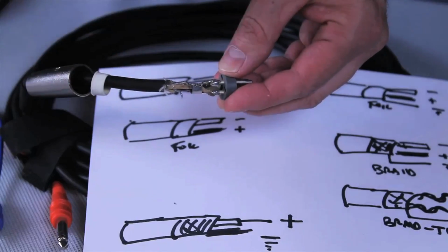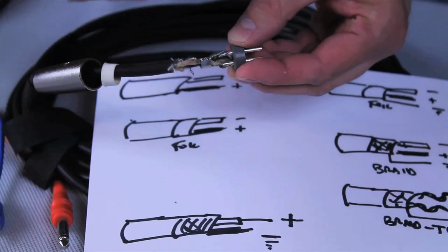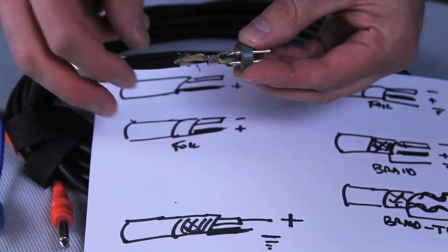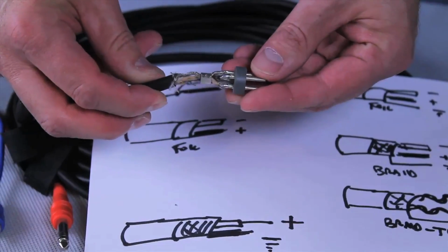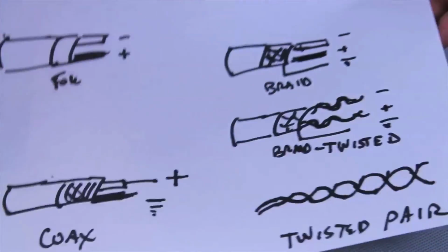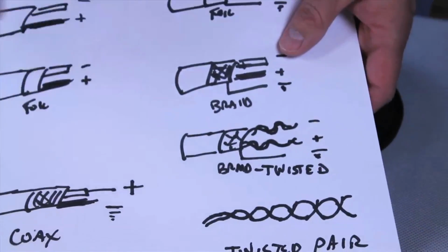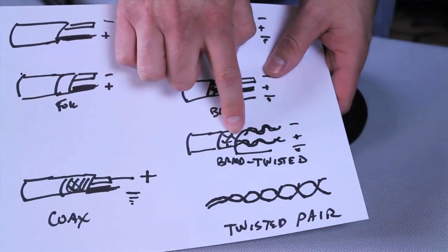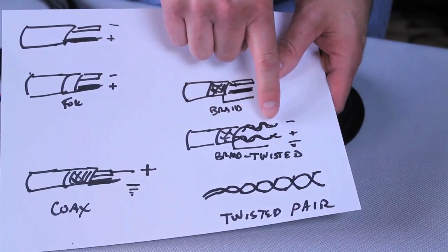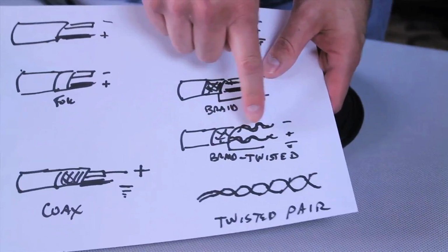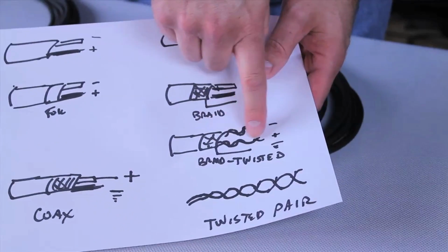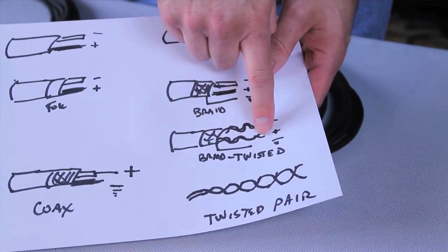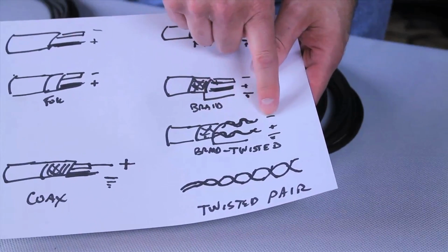In fact, the best kind of wire you can use on location has all this combined. It has not only one wire for the positive like this, it actually has 2 wires, rubber jacketed, and they are twisted together. For the ground or neutral, you have 2 wires that are twisted together. They're separated and rubber jacketed. And then you have the braid that goes around all that, which you pull out.